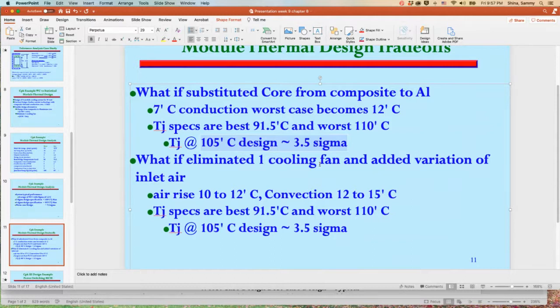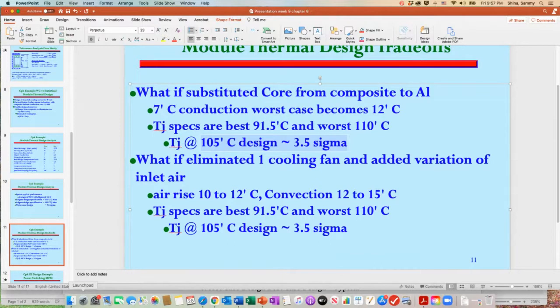Maybe tolerable, but certainly in a jet airplane, which has cost $50 million, and the pilot's life is worth hundreds of millions of dollars, they're not going to worry about a $350 cost for an additional fan or using a composite core instead of an aluminum core for the printed circuit boards to get better junction temperatures for the transistors in the printed circuit boards of the design.